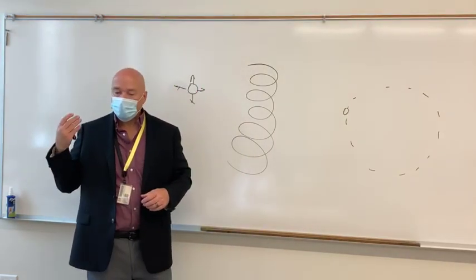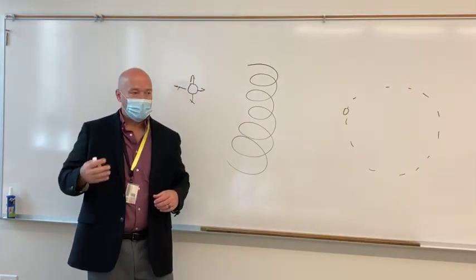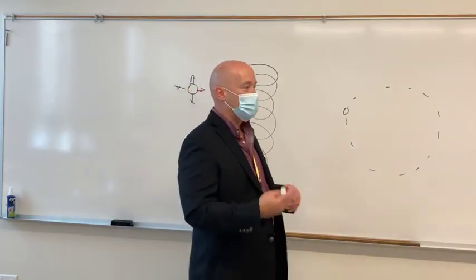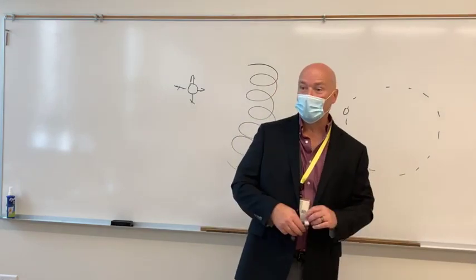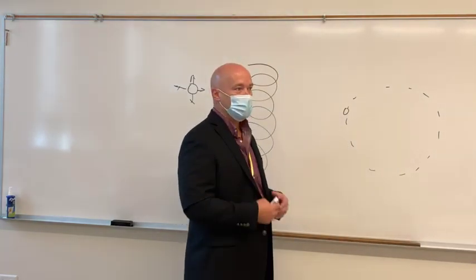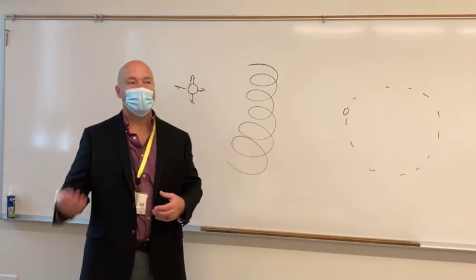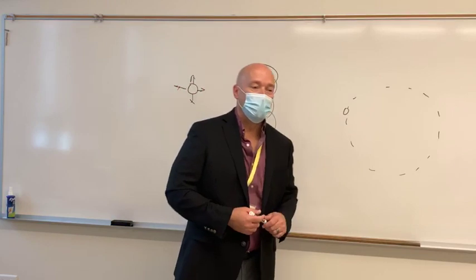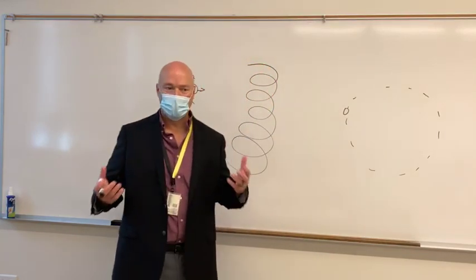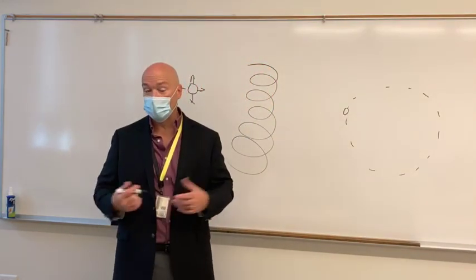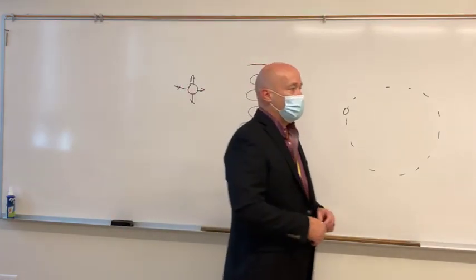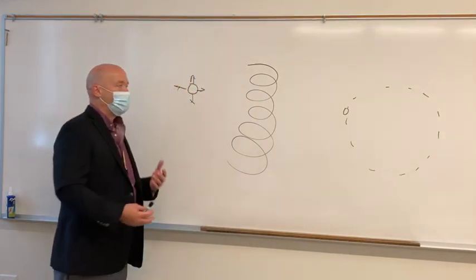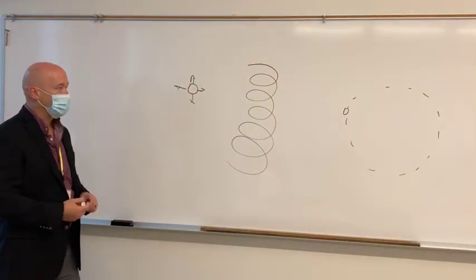But paramagnetic material is weakly attracted, so things that we tend to think of as being non-magnetic are truly magnetic. It's just that they're so weakly attracted that you can't observe it unless you have an extremely powerful magnetic field. Aluminum is an example. And then ferromagnetic materials are anything that is strongly attracted, and that would be things like iron. So iron is where we're going to live for the rest of the day for the most part when we're talking about magnetic fields and electromagnetism.